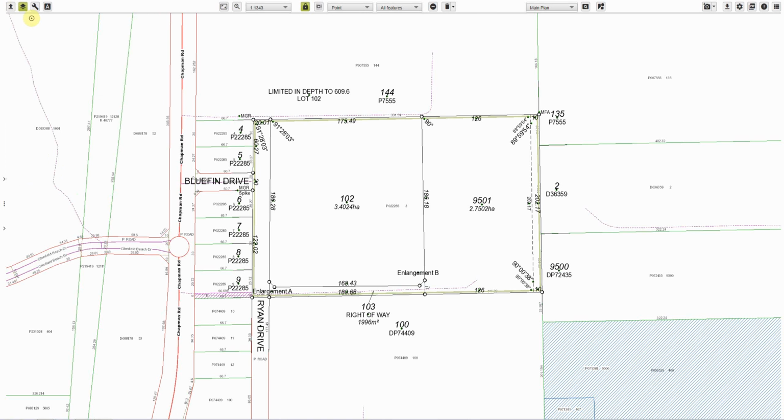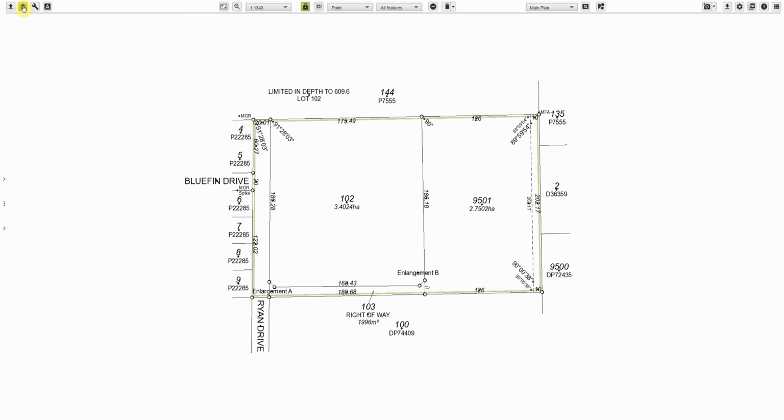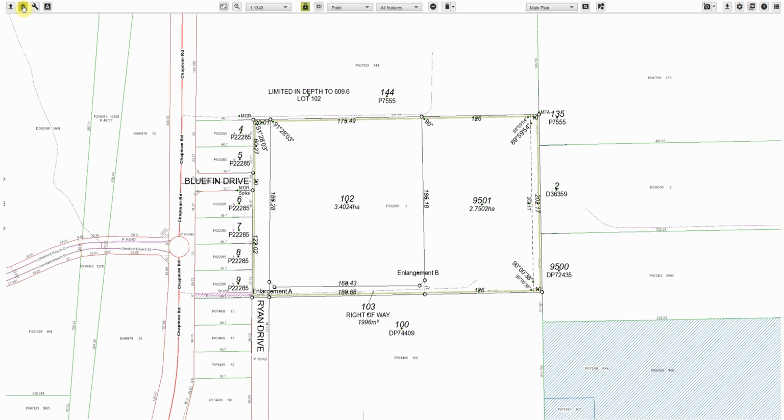The next button on the ribbon menu is the Show Hide Cadastre button. As you can see, presently the cadastre is showing, which is all the features around the plan. I can turn the cadastre off so that I can just see my plan features, or I can turn my cadastre on when I require the underlying cadastre. Showing the cadastre helps when generating lines for rebuttals.